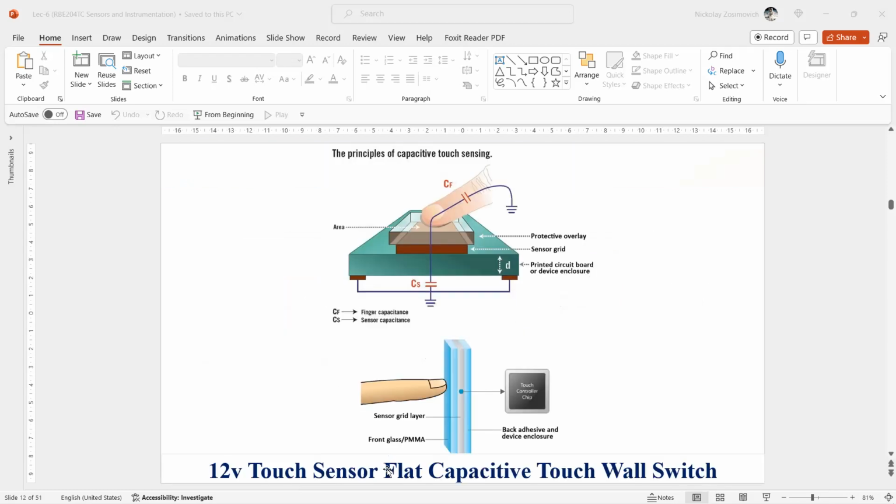An additional advantage of the differential configuration is the expanded dynamic range. What does it mean? It means that in the reference or initial position, the capacitances of the two capacitors are equal. Yes, right. So since only the difference is processed, the initial output signal is 0. And a small displacement results in a small output signal that can be electronically amplified without overload problems.